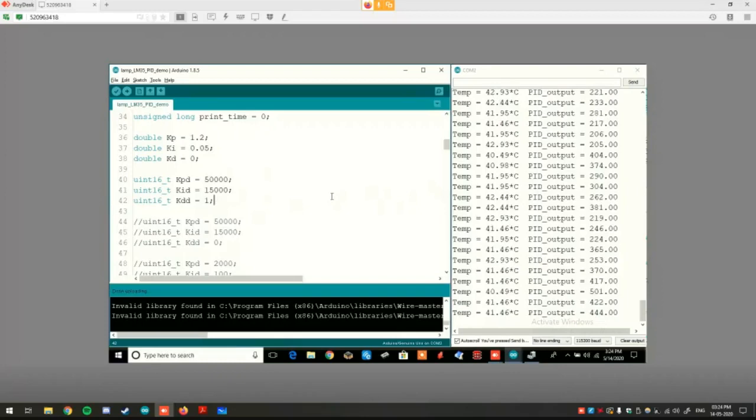One thing is that. Then the second thing is I think the hardware itself is quite slow. Then you can introduce a much more powerful or faster heater and see how the gain value changes. One thing to be noted is that the optimal gain value also changes depending on the set point at which I'm operating.